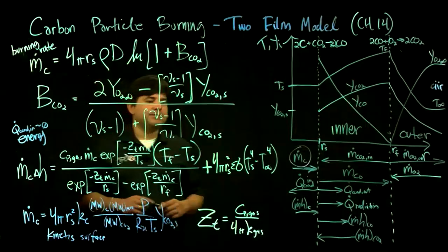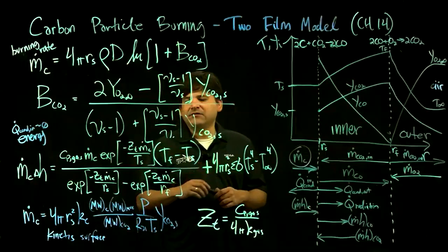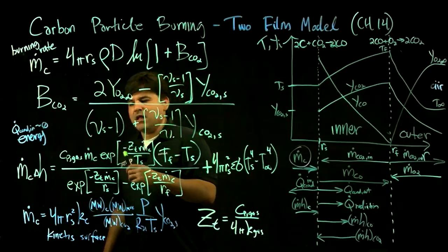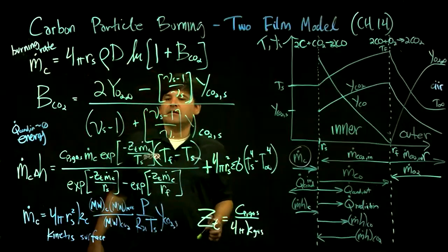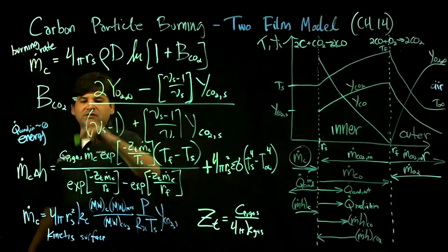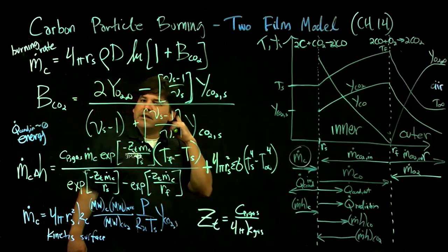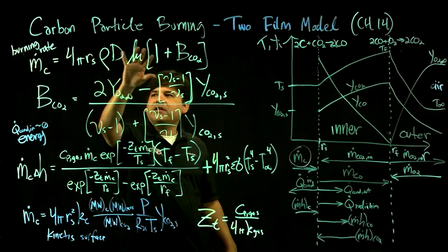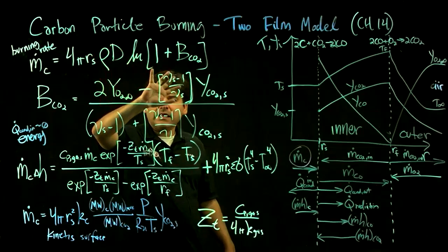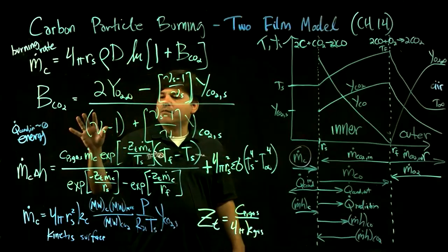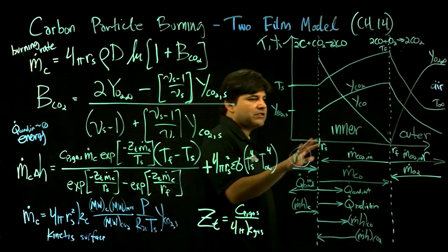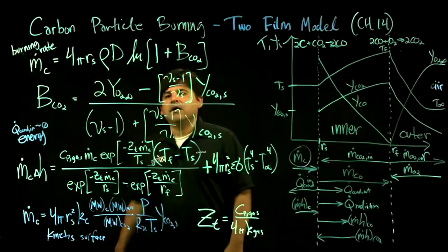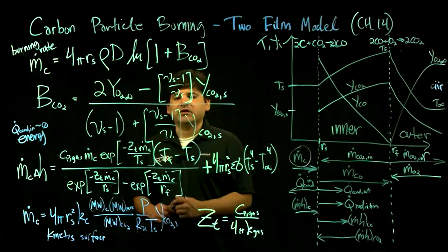So here, this energy balance can give you the flame temperature, the surface temperature, and the burning rate. And again, collapsing all this with the mass flow rates and the transport by diffusion, you can get this compact form. And that is combining all of the other analysis we did, all these other balances. And that should give you how all of these are connected.